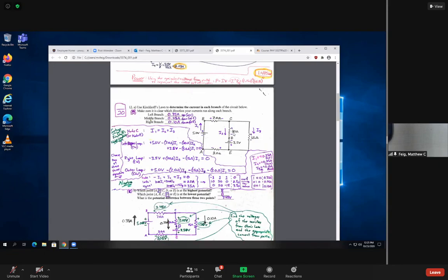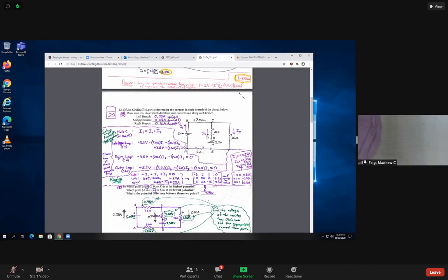Well, I can do Ohm's law, right? If you've answered part A, you got the current. So 20 ohms times what current? Well, now we know it's 0.25 amps. So 20 times 0.25, that is a quarter of 20, which is 5 volts. And since the current is labeled here as down, which is in accordance with this arrow pointing downward, which end of this is the high voltage end? That's what the plus there and the minus there is saying.